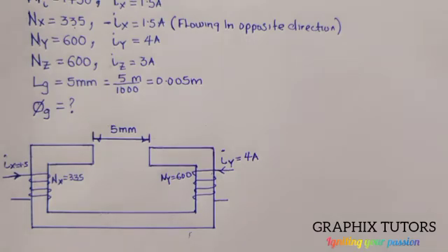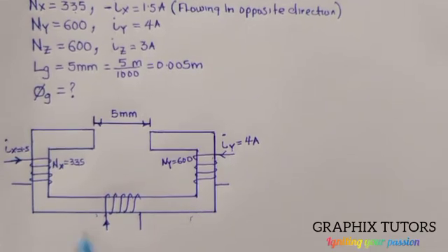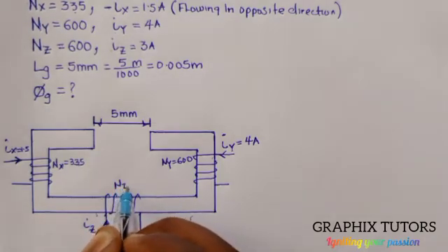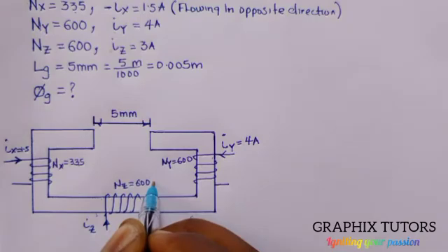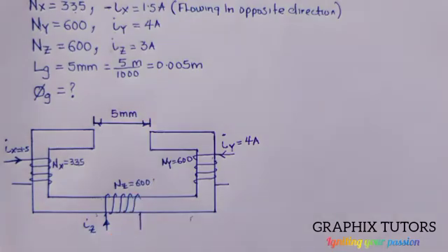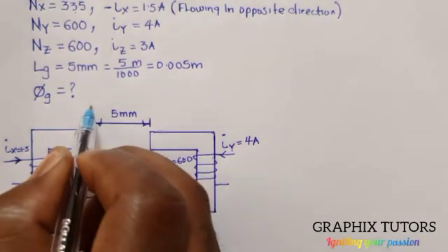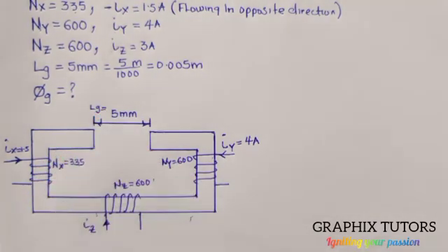Then the other one, there's a current for the IZ. So I subscript Z is the current flowing through the Z coil, and this is what? NZ, and that is also 600 turns. So this is what we have. IZ, NZ, right? Don't forget the LG, the length of the air gap. Then the entire length of the iron is called Li. So this is the magnetic circuit that we are drawing the diagram of here, right? So let us start with our calculation. Is that okay?